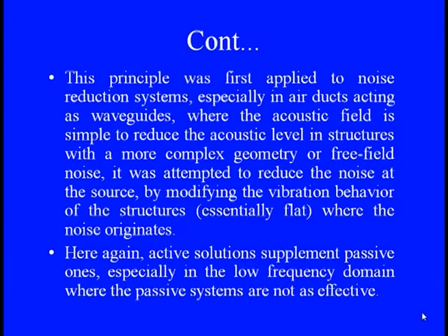And this was basically attempted to reduce the noise at the source by modifying the vibration behavior of the structure, means like when we are just putting the flat or uniform cross section, because from where you see this noise was generating. So, we can say that the active solution is a perfect supplement of the passive one, especially when we are talking about the low frequency domain, where passive systems are not as effective as compared to the active solution, because in the low frequency, in the passive solution, we are always adopting the spring.